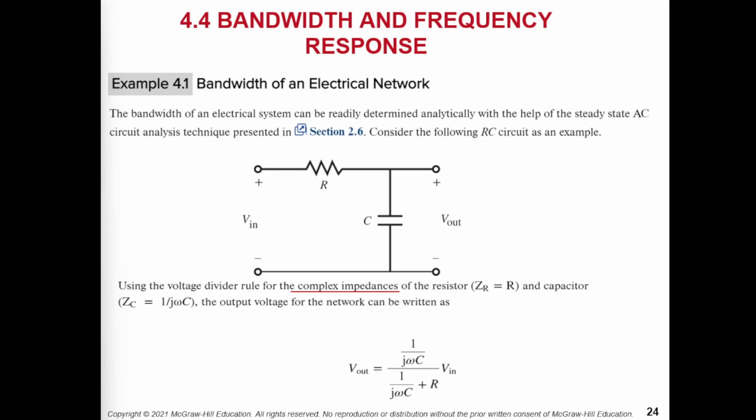Yeah, that's very good. Just doing some little conversation. Of course, this applies Kirchhoff voltage law. Then you can get the voltage division out of this capacitor, right? But we are more familiar with the resistor than the capacitor. So how do we get the fraction of the resistance out of the equivalent resistance? We need to calculate the impedance, right?